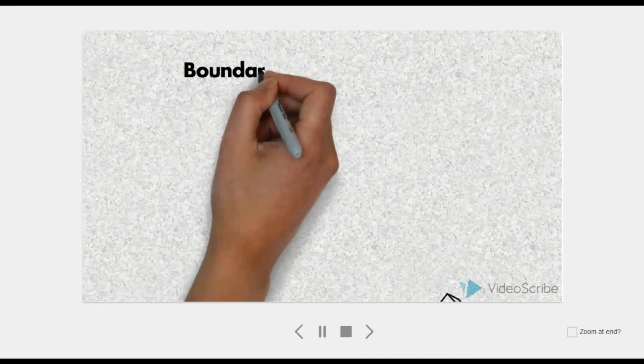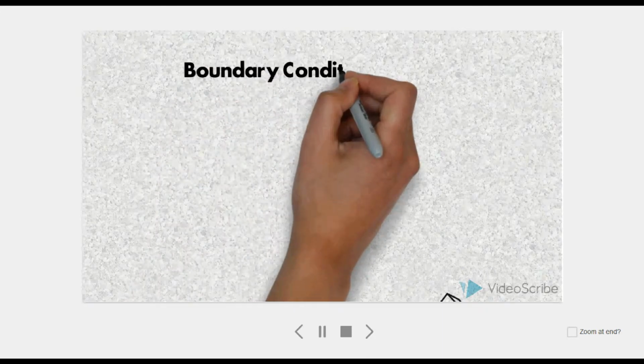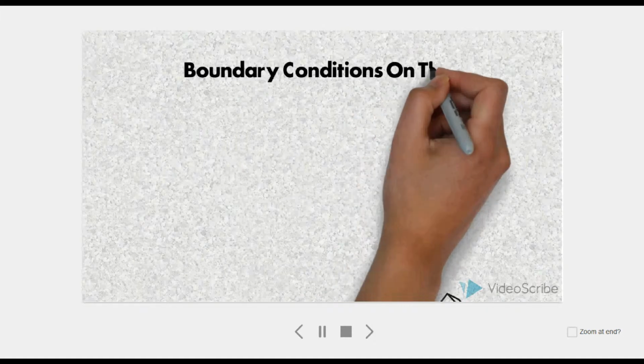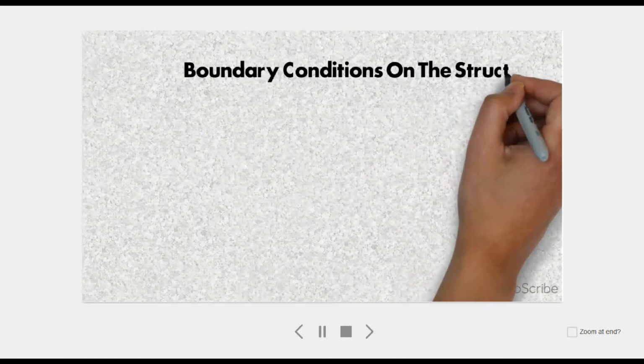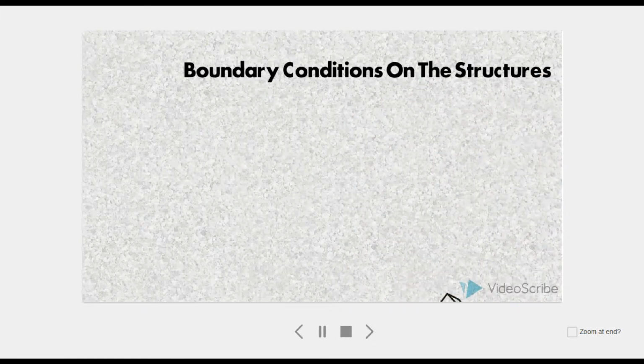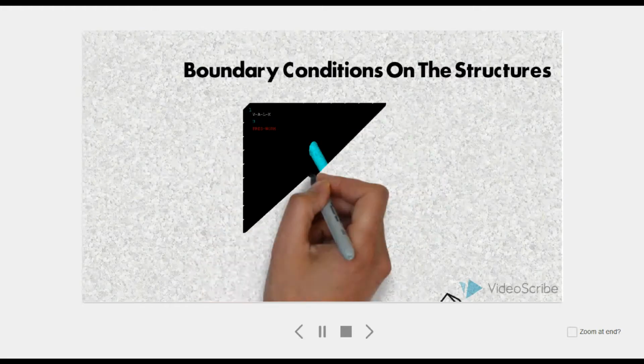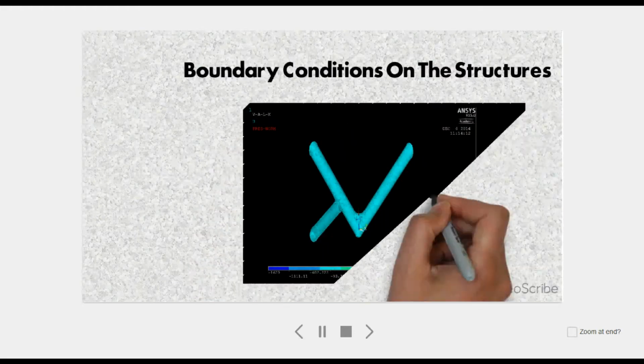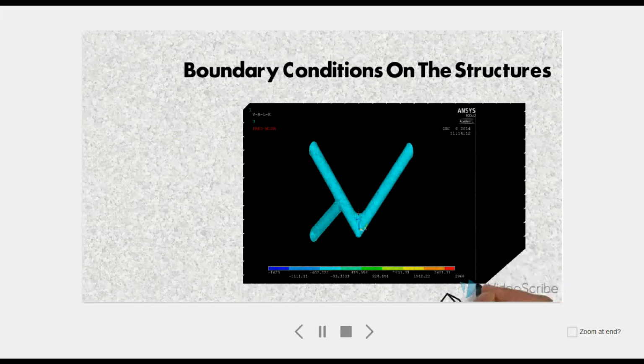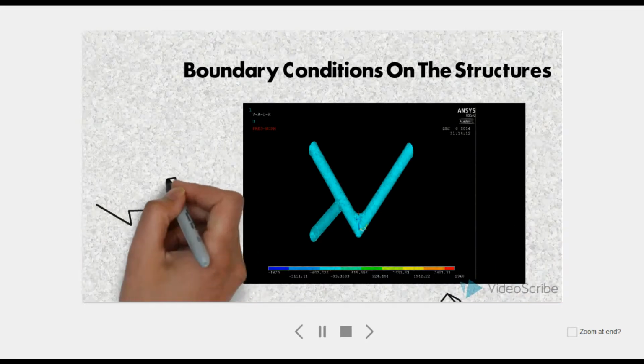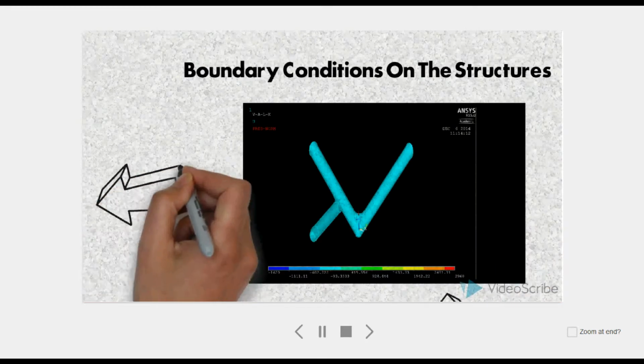Boundary conditions were applied to the Ansys model to mimic the boundary conditions that were given in the Top-Op optimization. Those boundary conditions can be seen below in the picture. A load of 700 pounds in the negative Z direction, 236 pounds in the negative Y direction, and 118 pounds in the positive X direction were applied.